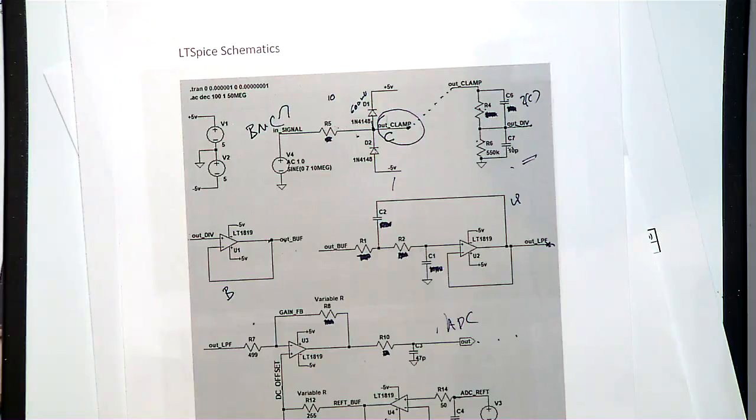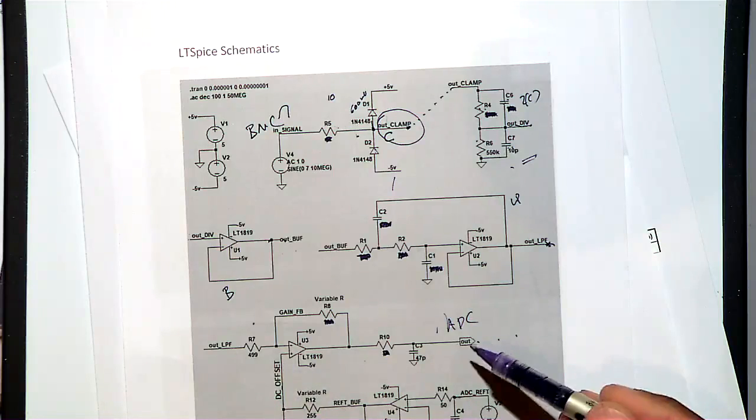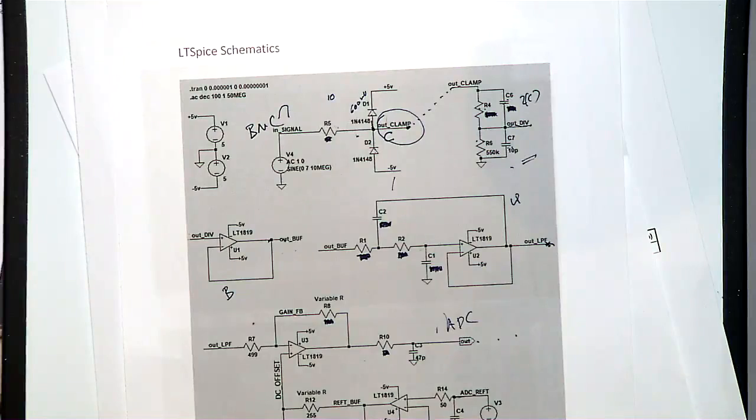Then you may also have to plot the output of the ADC. So we will tell you where to measure in the simulation report. This is the first report you will be generating, and it is not a complex thing. With your knowledge, if you know LTspice, you can do it in a couple of three hours' time. Realistically, you can finish your simulation report, because you know what each block does.